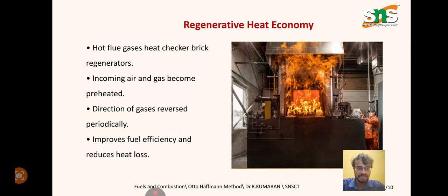The direction of gases is reversed periodically, so that heat is supplied in a stable way. There won't be any fluctuation here since the heat is supplied from the bricks. That's why the hot regenerators are there. It improves the fuel efficiency and reduces the heat loss. That is very, very important here. It reduces the heat loss.